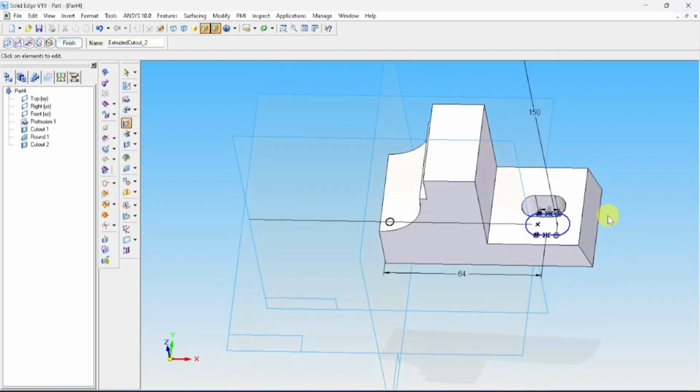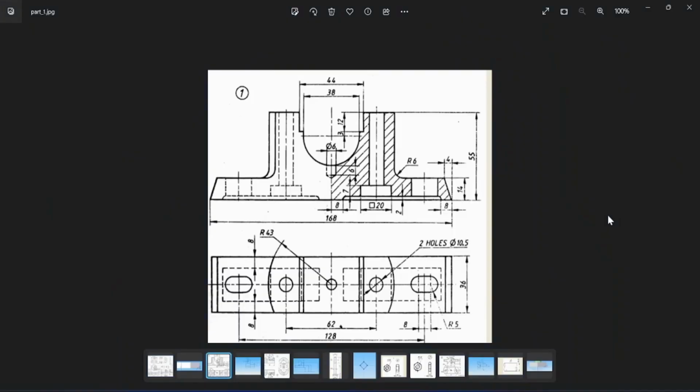So next tip is we need to do this stud hole. Up to here it is a round hole, and here it is a square hole. This square hole, we need to do upper side of 20 mm each, and here up to a depth of 7 mm from the rectangular cutout.